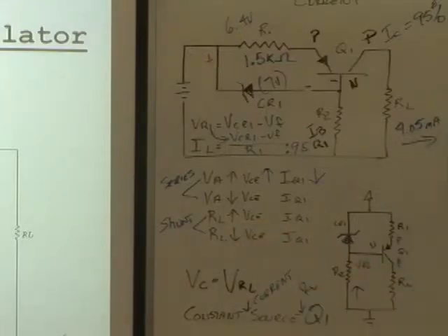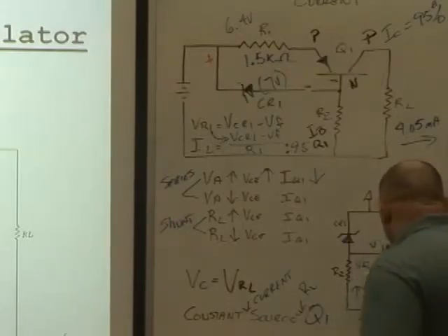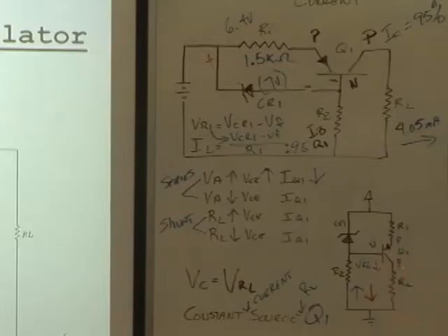Line voltage decreases. I total is going to want to do what? Well, not want to. It's going to decrease. So the circuit has to compensate for that. It's the opposite. Now, if I go like this, VR2 voltage drop's going to be less now, isn't it? Yes, sir. So now less potential on N-type material is going to cause that depletion region to do what? Forward bias, and the transistor will conduct more because I need more current to the load to maintain that constant, don't I?